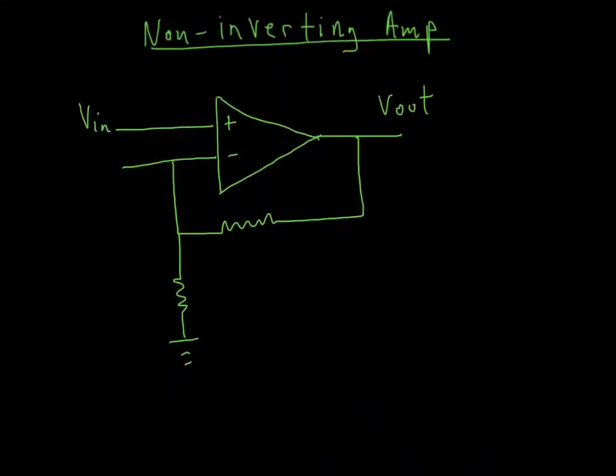This will be our last example for this screencast. This is the second example that one usually does when learning or teaching about operational amplifiers. So here's the non-inverting amplifier, and you can see that the input is on the positive, the non-inverting input. And once again, we have feedback on the negative side here. And oh, I forgot to label my resistors again. Not a problem. Let's call this one R1 and R2. All right. So using golden rule number 1, we know that the positive input to the op amp has to be the same as the negative input. So we can label this as Vin right over here.